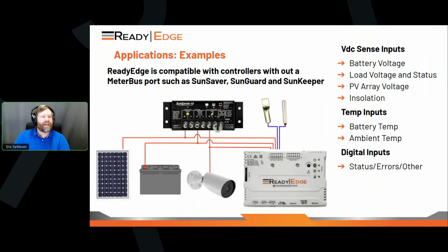And then I want to jump back because I really want to drive home this idea that the ReadyEdge is excellent as a standalone device as well. So this example is again showing you how we're using a SunSaver, which does not have a meter bus port. And this could, again, not even be a Morningstar device. We're measuring all of the important aspects of the solar system using the voltage inputs here.